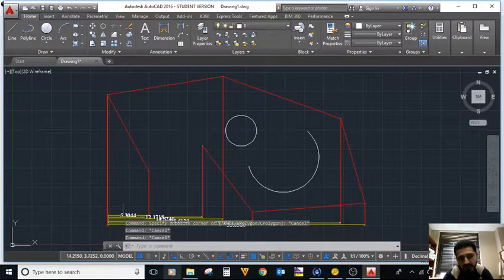Okay, so as you can see, we have 5.3044 from here to there. So this is your baseline, and everything else is being measured from that baseline all the way to here. So now we would get to know the distance from the baseline to this corner, to this corner, to that corner, third and fifth, all the way till the end. So the overall length from the far east to the far west is 33.0580.